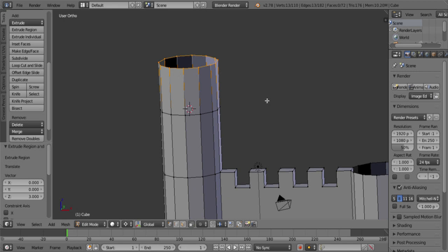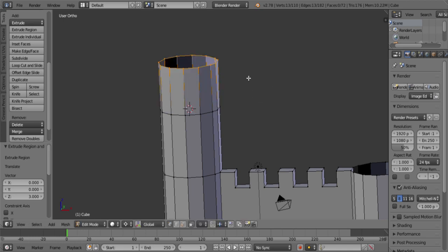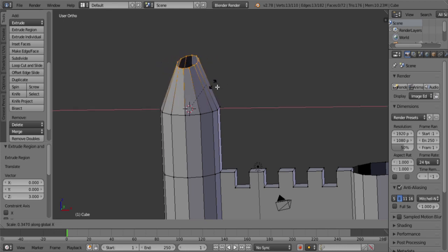Now look what happens. I'm going to scale and I'm going to type in 0, but it's now scaling towards the cursor. I just right click to undo this one. I could also scale in every direction except the Z direction, and that's what we need right here. I press scale and I could press X, and it's only extruding along X. Y, it's only extruding along Y. I can also press Shift Z, and now it's scaling along X and Y. If you press Shift Z, it scales not along Z, to be more precise.